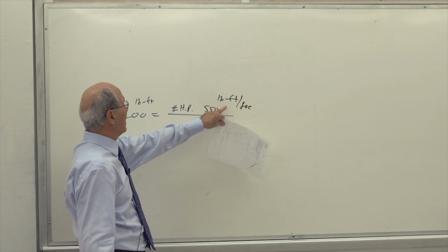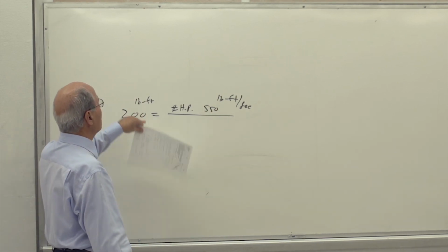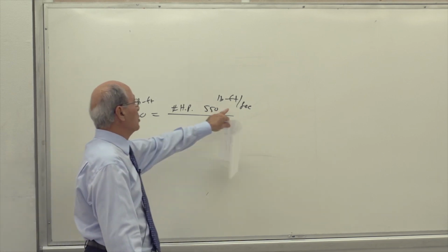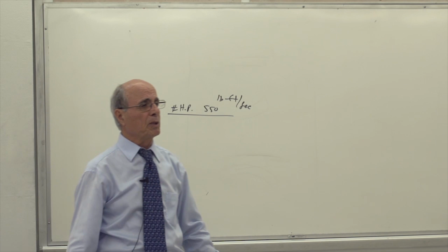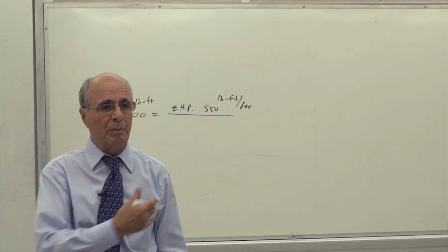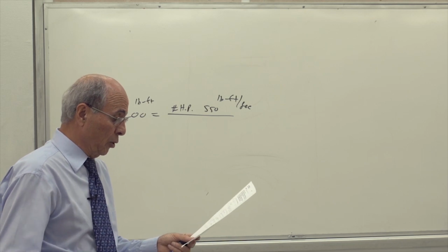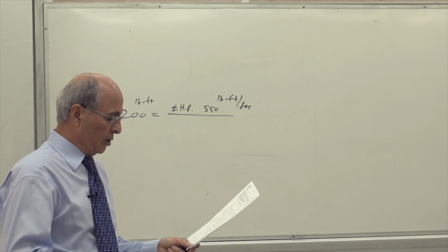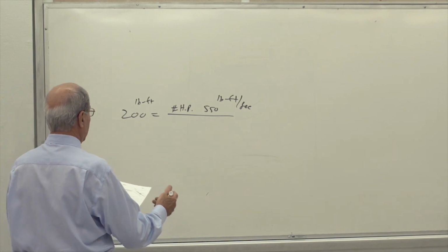Therefore, this is pound-foot. This should stay pound-foot. Actually, if this is pound-inch you're calculating, you have to divide it by 12, or you multiply. If you are putting this in pound-inch, you have to multiply this by 12. I mentioned that. You have to match the unit. Many people do not even pay attention to the unit. I don't know how you do the homework, because these are all repeated in your homework. But, of course, many people got this part correctly.